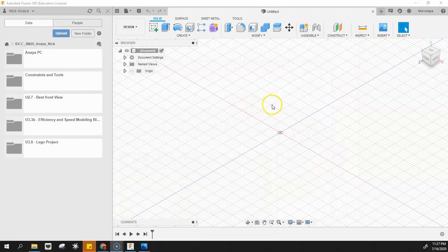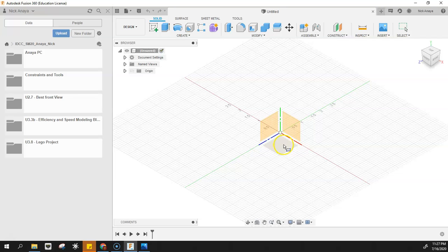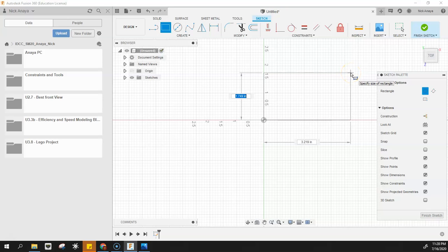To begin, we're going to start with a sketch. I'm going to right click, pick sketch, then do a 2-point rectangle, selecting the plane on the bottom here. This is my XY plane. I'm going to start off at the origin and move up and to the right. The Lego's not very big, and so his size is actually going to be 0.31. Then hit tab and do 0.62.